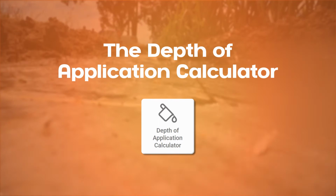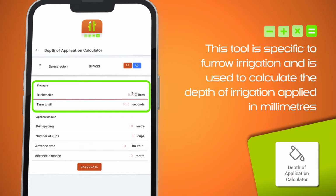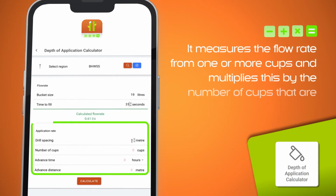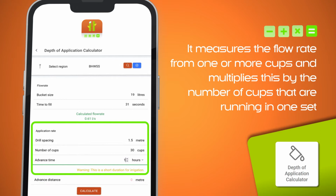The depth of application calculator. This tool is specific to furrow irrigation and is used to calculate the depth of irrigation applied in millimetres so that it can be considered to be of equivalent rainfall. It requires some in-field data collection to measure the flow rate from one or more cups and multiplies this by the number of cups that are running in one set.